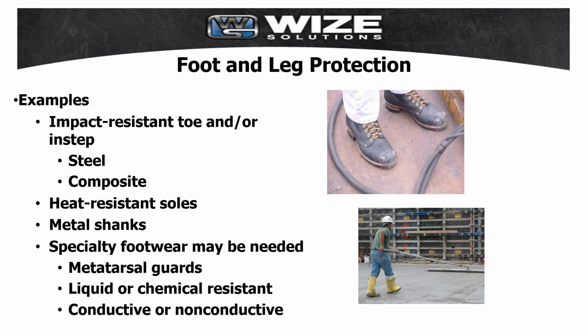Safety shoes have impact-resistant toes and heat-resistant soles that protect the feet against hot work surfaces common in roofing, paving, and hot metal industries. The metal insoles of some safety shoes protect against puncture wounds. Safety shoes may also be designed to be electrically conductive to prevent the buildup of static electricity in areas with the potential for explosive atmospheres, or non-conductive to protect workers from workplace electrical hazards.